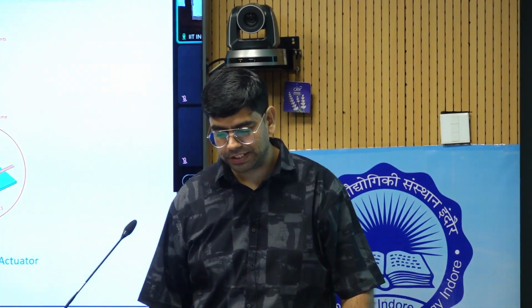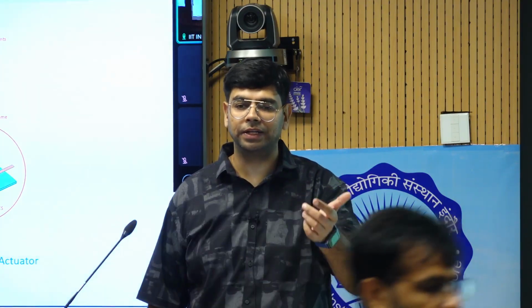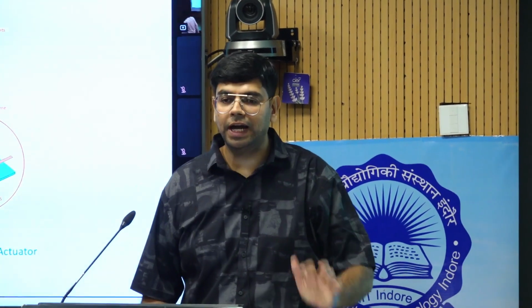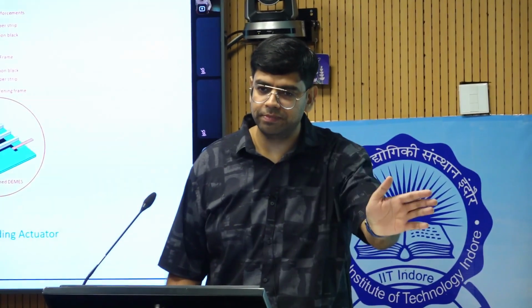We have already seen this stretching mechanism. Then what we have done, we have stretched that membrane. And in that pre-stretch mechanism, we have all these ingredients ready with us: frame, stiffeners, carbon grease. One by one we are going to put them. Then with the help of a razor blade, we cut that component. Initially in the assembled view, it will look like this. When you cut it, this is the basic experimental mechanism that we have followed.